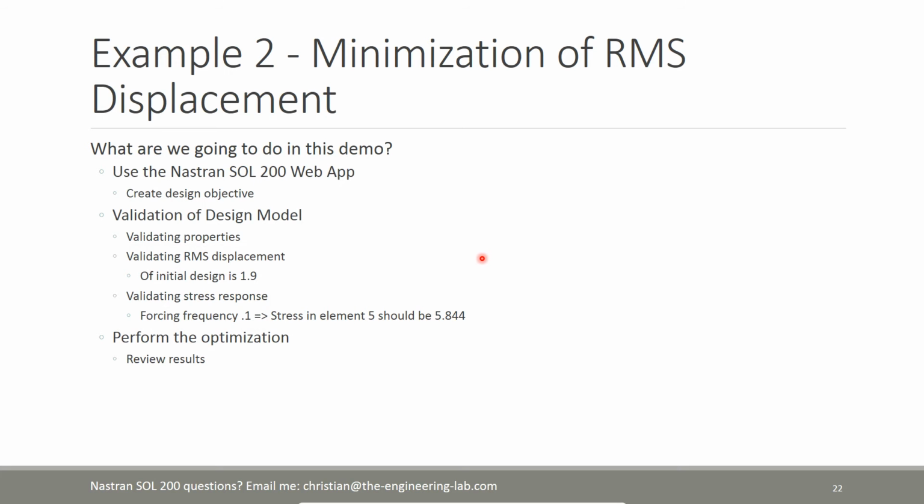And now there's a lot to cover here. I won't show you how to do this or how to view the results in Excel or Patran or any of that. What I want to do is show you how to confirm that you've properly set your values. Once you optimize large models, you want to make sure that you've properly configured your design variables, your design constraints, or your design objective. Every now and then you may have singled out the wrong design variable.